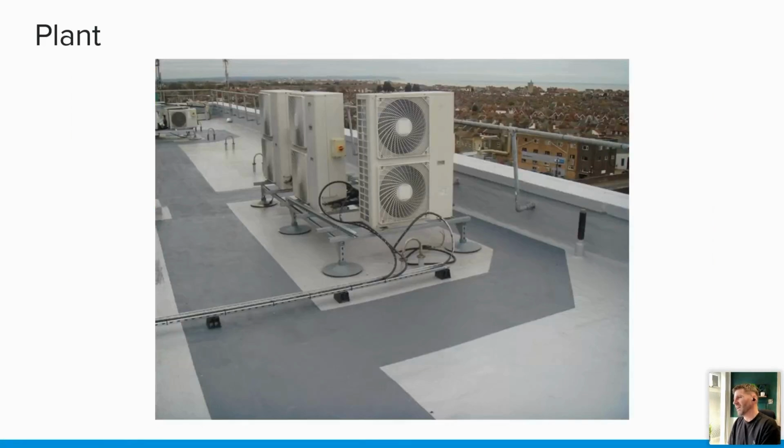These are great ideas, big foot systems and things like that, because what can happen here is these legs can be locally lifted, so you can lift one or two of the legs, obviously support the system first and then lift a couple of the legs, get the waterproofing underneath, and do things like that. A lot easier. And obviously you've got access underneath here if you wanted to apply a coating or something like that. So these for me are really, really good systems, these kind of big foot type systems.